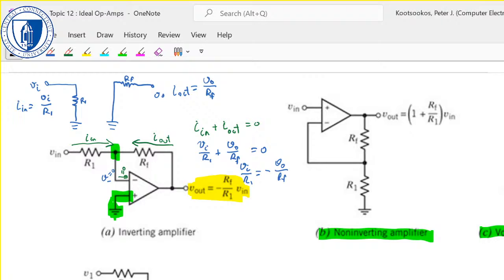And sometimes you'll see it just done electronically using a 741. More often in industrial applications you'll see that buffer done optoelectronically. So there's no electrical connection between the input and the output. And there's effectively an LED on the input side and a phototransistor on the other side. But it's set up effectively like a buffer. A unity gain amplifier.